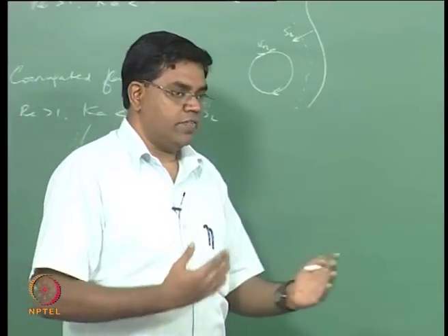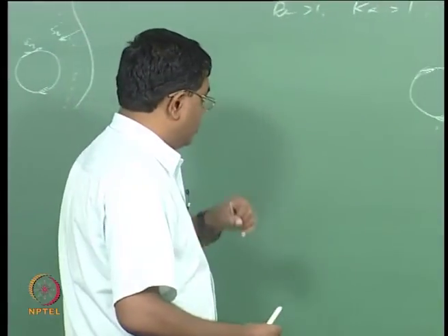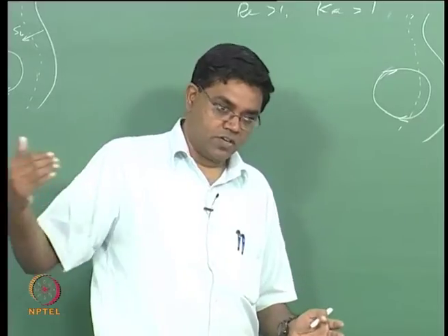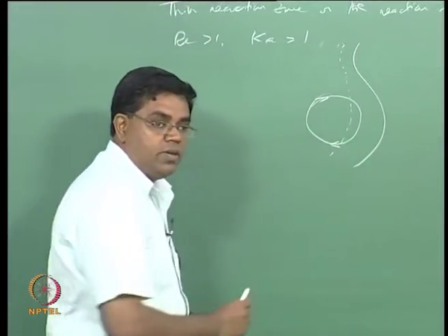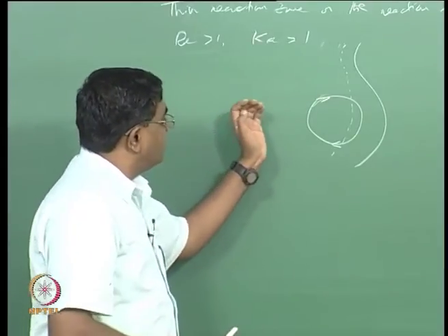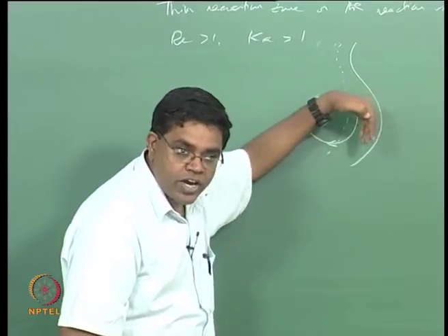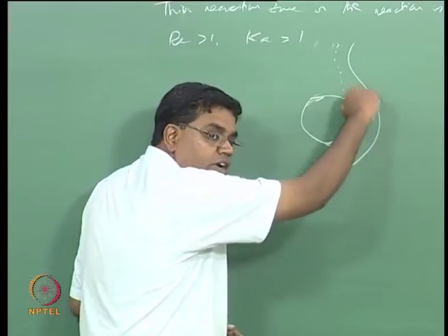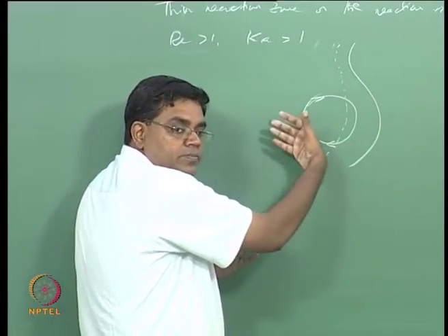So you have heat and mass transport happening in the preheat zone, which is now, in addition to the molecular transport that happens because of temperature and concentration gradients, also happening because of the eddy. That means this eddy is now taking the reactants and putting them into the preheat zone for the reactions to consume, and taking the heat from the preheat zone and bringing it ahead to the reaction zone and heating it up, right.